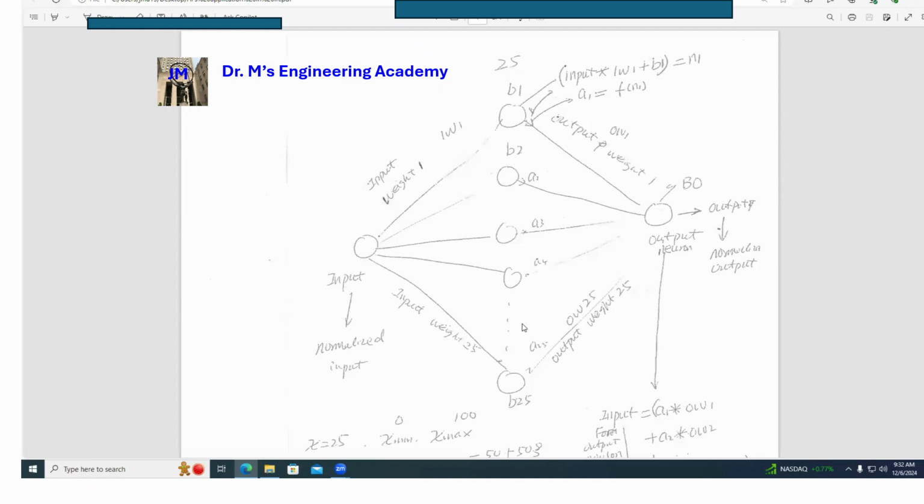Because the rigidity of the arm is bad, the hand will be pushed back. Even though it's a very small pushback, when you finish the polishing, if you do not do anything, the final dimension of this surface will not be the dimension you are desiring, you are expecting.